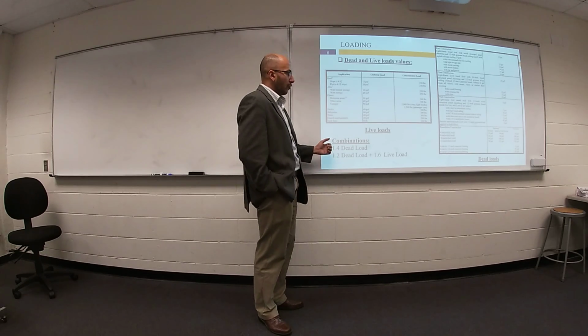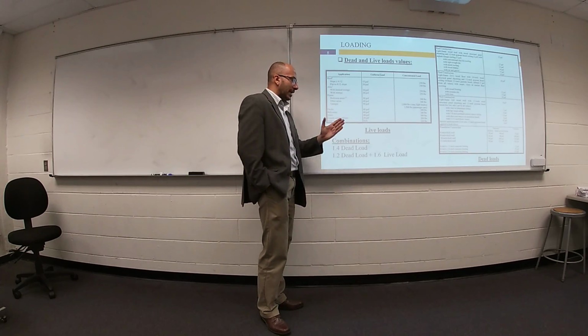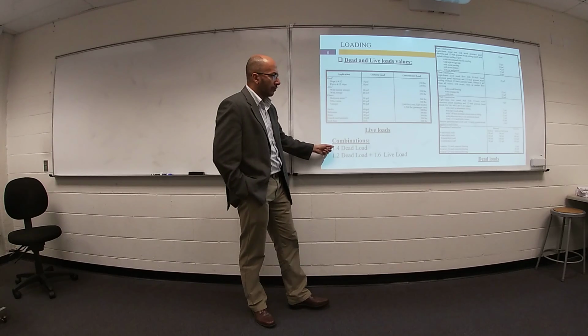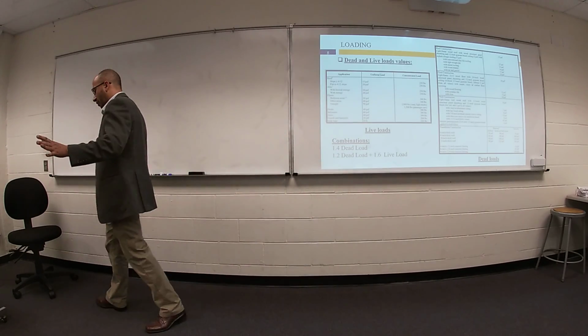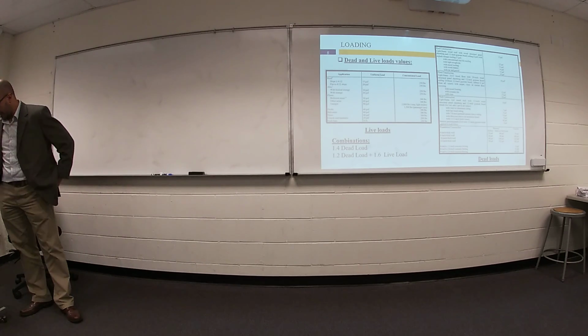And remember, we have two main combinations for dead and live load. The first one, 1.4 dead load. The second one, I'm sorry, 1.2 dead load plus 1.6 live load.